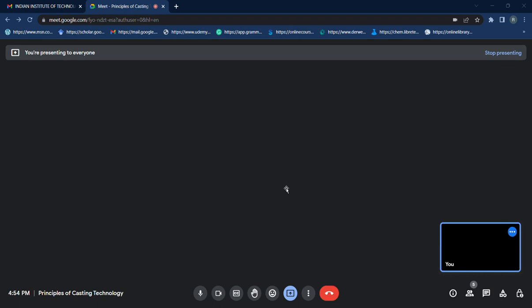These are all the empirical formulas, and mostly they are not asked in the exam, but if they are asked, the values will be given. But you need to have an idea of how a casting is designed, how the parts are designed. That's why I have introduced this. From here you can see Ln is the maximum of d by 2, and Dn is Ln plus 0.2 d for a side riser of plate casting, and these are the different ratios of Ln, Wn, and Hn.